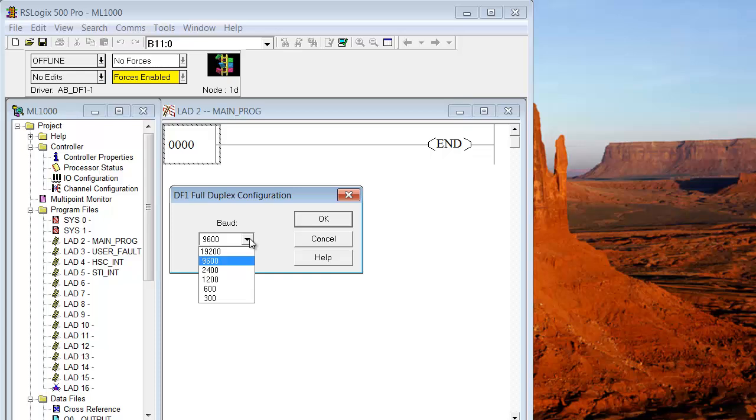We're not going to explain baud rate right now. Basically it means the communications rate. Because this is serial communications, both ends have to agree on a baud rate. Otherwise there's going to be confusion because they're expecting the serial data to change state at a certain rhythm.